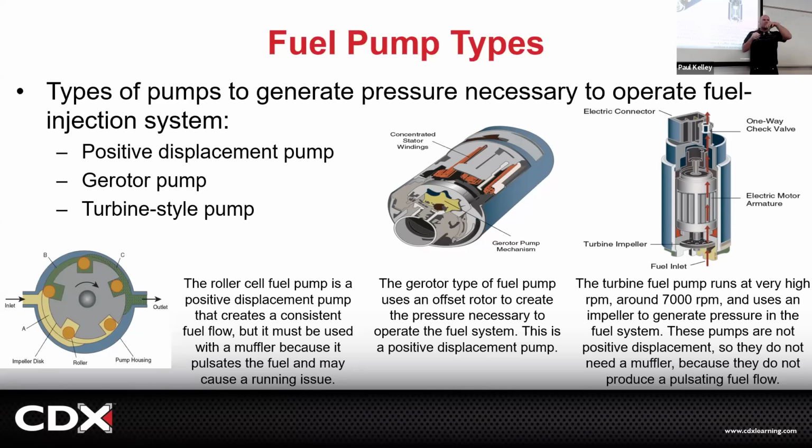Like the light will dim and stuff like that. When you're trying to move a motor from a stop, it draws a lot more amps. Every rotation, my motor was trying to get itself moving after the dead segments. It would draw more amps. It was periodically blowing the fuse once in a while, depending on when I started the bike, if it got stuck on the dead segments. It was a really interesting diagnosis.